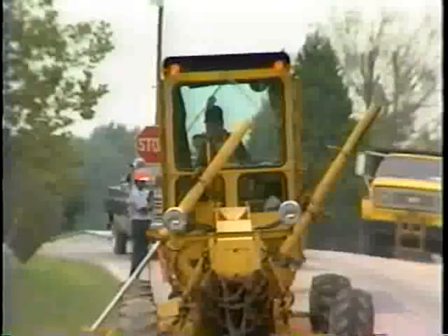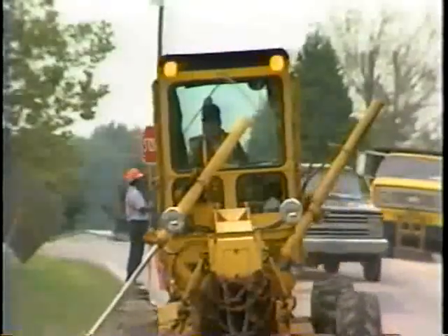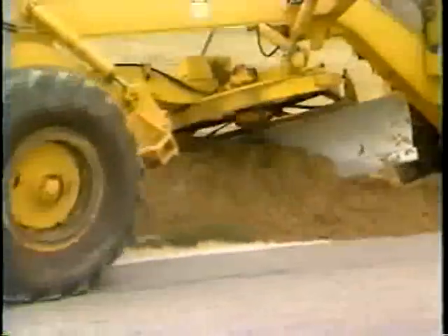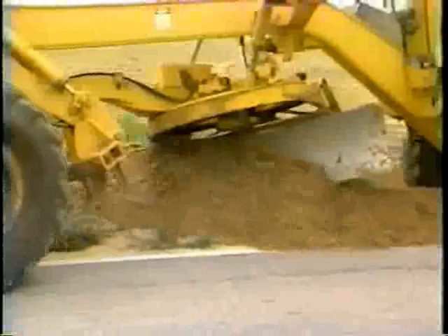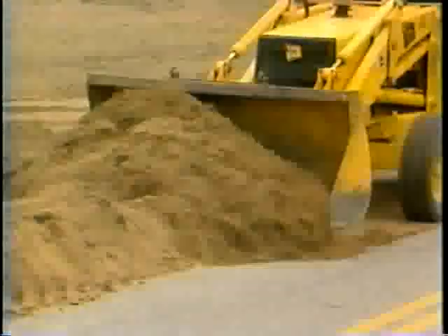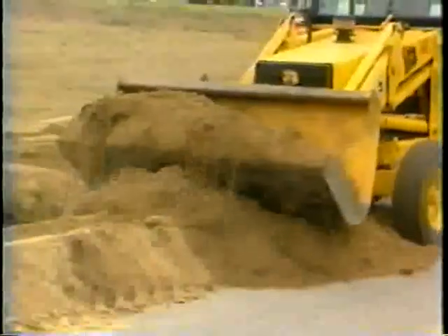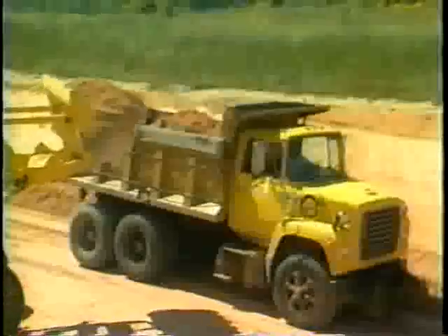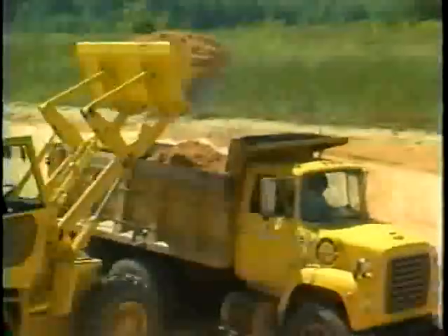One thing to be considered prior to this operation is the location of additional material. Possibly, material can be recovered from ditch maintenance performed in conjunction with the shoulder repair. Ditch maintenance or high shoulder repair performed on a nearby roadway can provide excess material. Borrow material or stockpiled material can be hauled from the nearest available source. The quality of the material and the haul distance are important factors to be considered when obtaining this material.